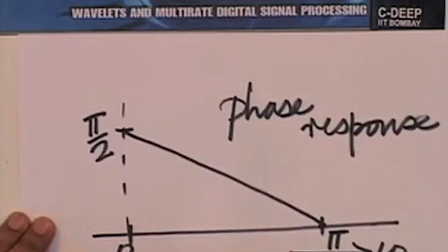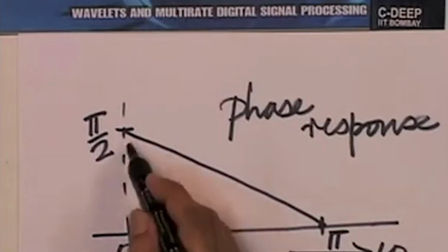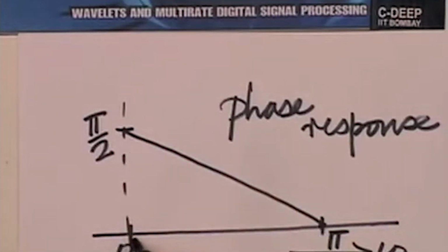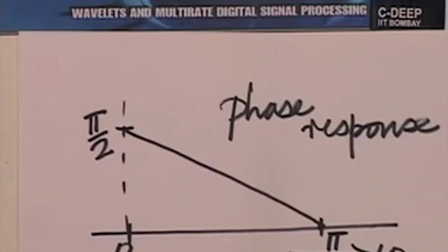Now, once again we have linear phase. Well, almost, not quite linear. If it were strictly linear phase, this would have been a straight line indeed, but a straight line passing through the origin. So, it is not really linear phase, this is called pseudo linear phase, seemingly linear phase. In fact, for completeness, let us draw the magnitude and the phase response all the way from minus pi to pi for both of these filters now, for the sake of completeness.